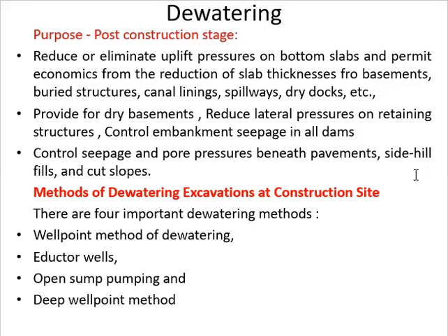And also they provide dry basements, reduce lateral pressures on retaining structures, control embankment seepage in all dams, and they control seepage and pore pressures beneath pavements, side hill fills and cut slopes. There are 4 important dewatering methods: well point method of dewatering, eductor wells, open sump pumping, and deep well point method.